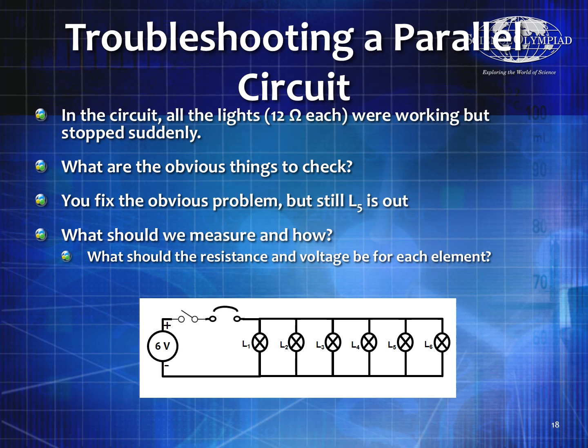Well, that tells me that pretty much all of those light bulbs are working. Because if it's 6 ohms for each individual light bulb and you have 6 in parallel, that should give me 1 ohm. If any one of those was shorted, I would have 0. Now, if it came back 0 ohms, I would know I have a short, and then I have to take out each light bulb individually and check them.